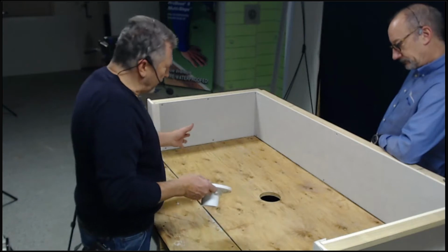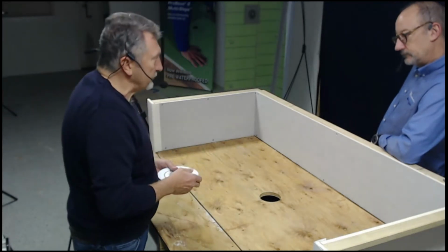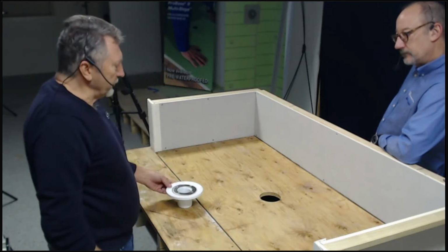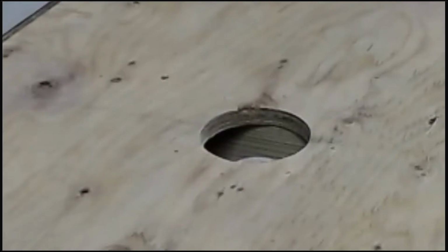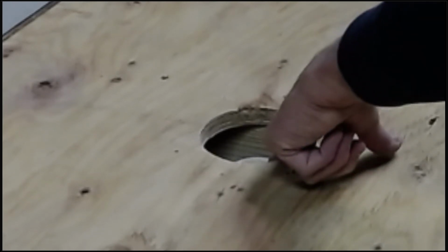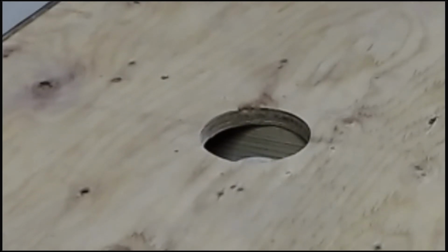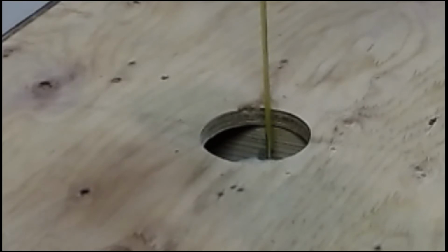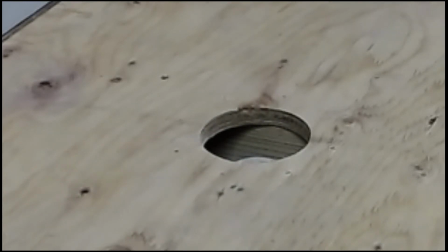So I've identified my drain area, which is going to be center in this case, and my floor joist is not interfering with my rough-in plumbing. First of all, you're going to want to cut your stub out of your trap to 1 3/4 inches below the top of your substrate. That's for this drain. Yep. So I confirm that is cut, ready to go.